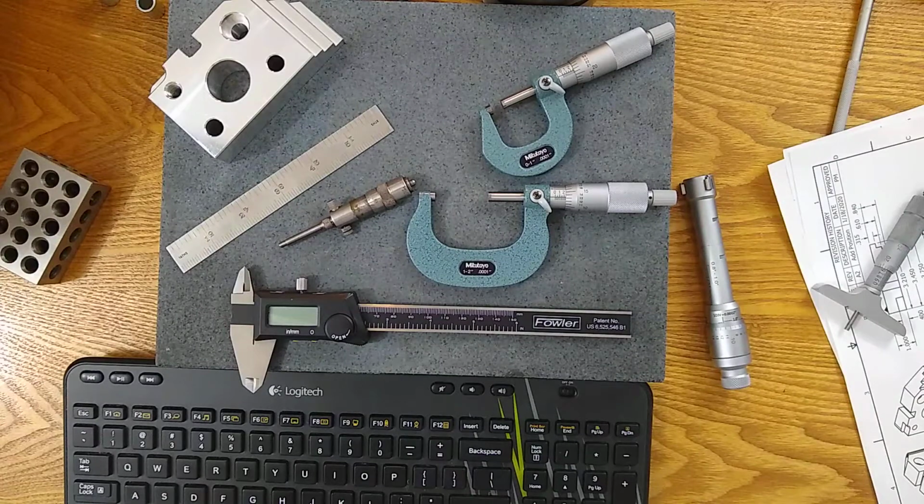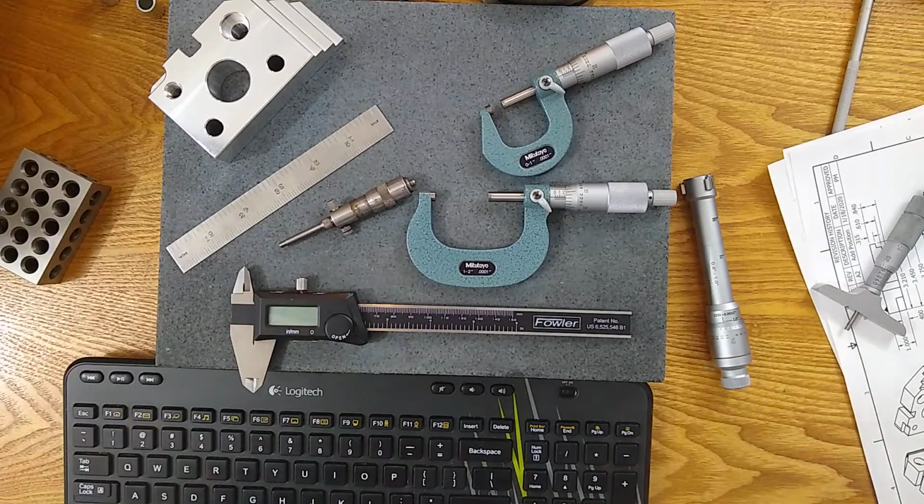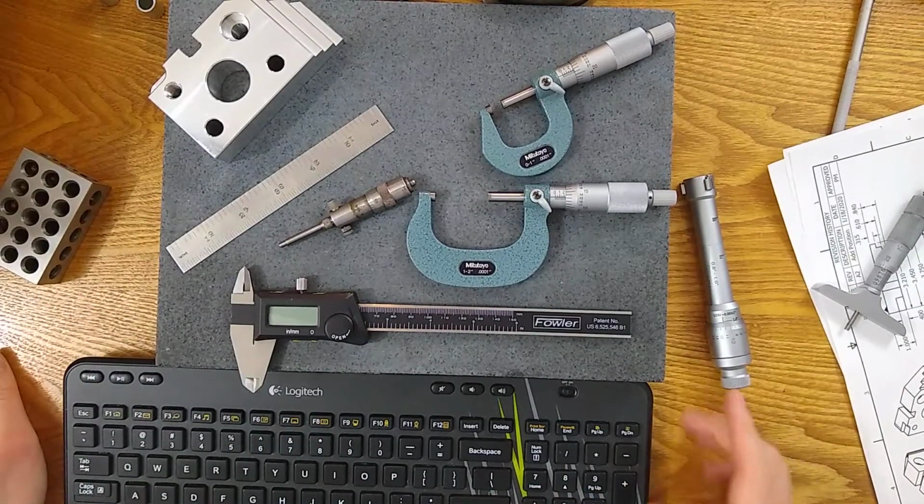And you'll notice the windows are much, much tighter. For a 10-to-1 ratio, 2/10,000ths with a 5 micron resolution machine, many tolerance zones are bigger than 2/10,000ths. Some are not. So you'll still need to decide if you can use a CMM. It's one of the more accurate gauges, and as you compare all these numbers, you'll see why. But still, it's not universally applicable to all situations.